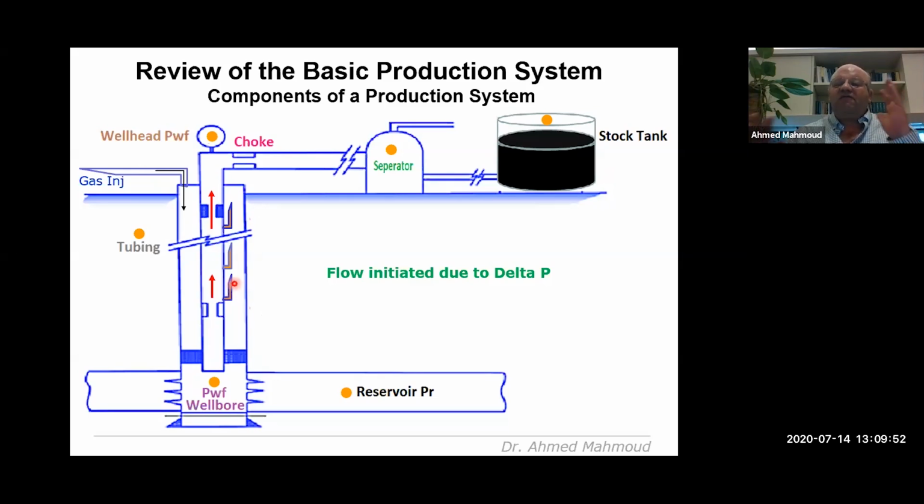The mixture of the oil and the gas lightens the density, reduces the hydrostatic pressure, and lightens the total burden of fluid weight in the tubing and acting on the wellbore. It will have enough force to apply delta P, which will be able to now deliver hydrocarbon fluids to the wellhead and complete the cycle all the way up to the stock tank.